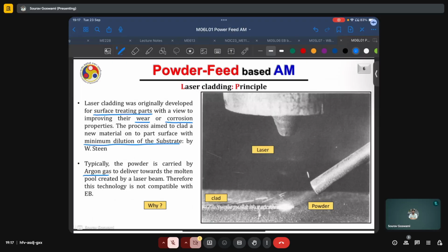As we saw, for the case of electron beam based wire additive manufacturing processes, to ensure that the beam of electrons reached the target surface and could deliver energy to it for melting, fusion, and deposition of the metal, we had to ensure an uninhibited and direct path of the electrons to this target surface. For this, we ensured a vacuum in the working region so that no heavy molecules or other heavy particles could be encountered in the path of the electrons.